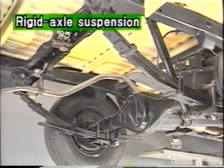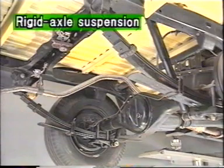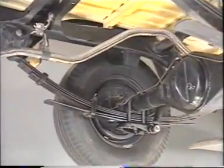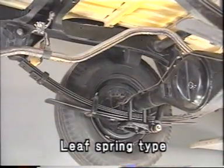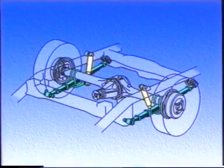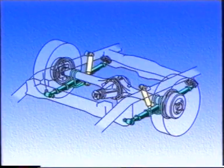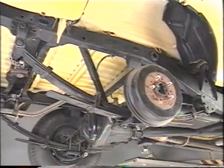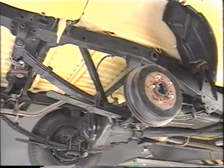Now let's take a look at the types of rigid axle suspension. Leaf spring. In this type of suspension, leaf springs dampen the shocks received from the road surface. This suspension also functions as a suspension arm for holding the axle in place, which means that a linkage system to maintain proper positioning is not necessary. Its construction is simple but comparatively strong. For this reason, this type of suspension is used for buses and trucks.